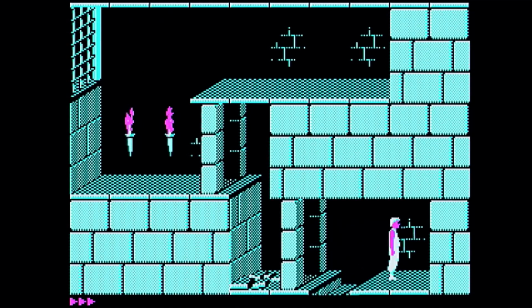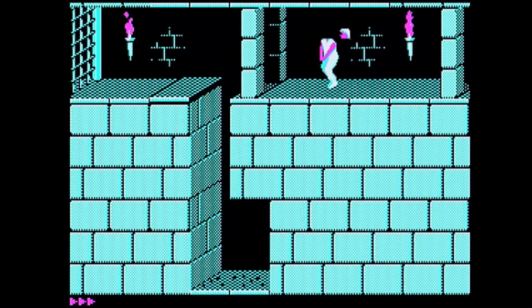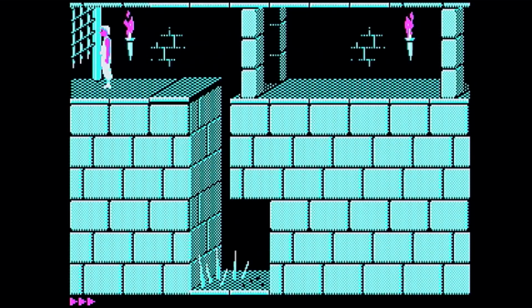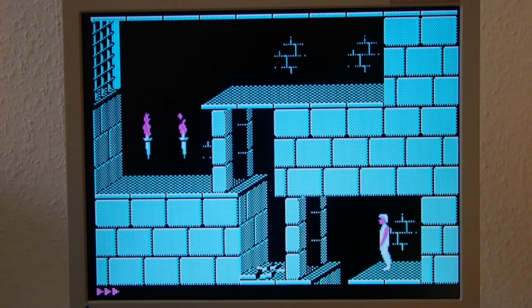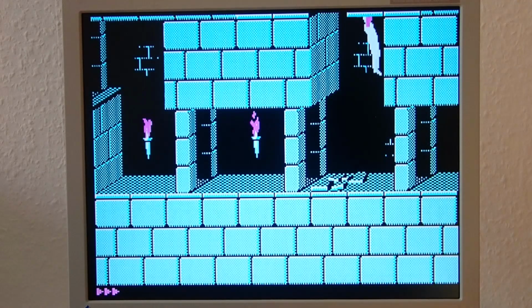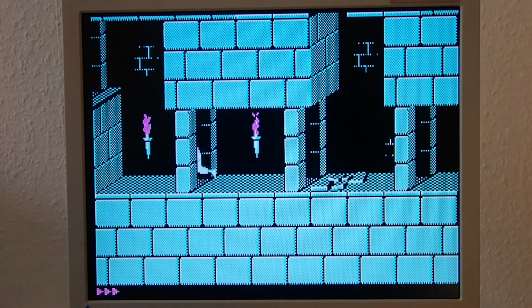But with such a chain of converters, with the graphics adapter itself, my MCE adapter, gbs-8200, VGA to HDMI, and the HDMI capture device in the end, it makes it a little bit complicated to tell what exactly impacts the image quality and how much. At least on the monitor, which was connected directly to the gbs-8200, the image was a lot sharper. What makes me think that the VGA to HDMI converter could be one of the reasons for blurring.